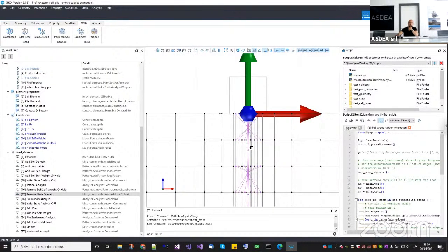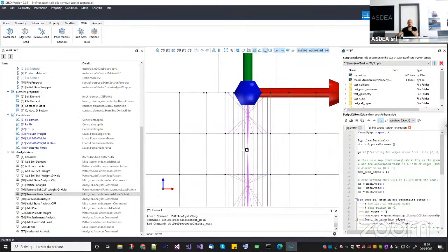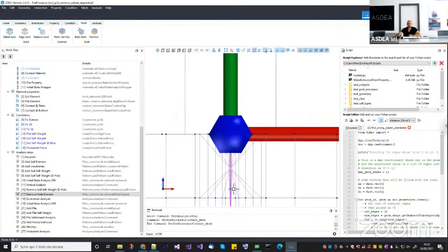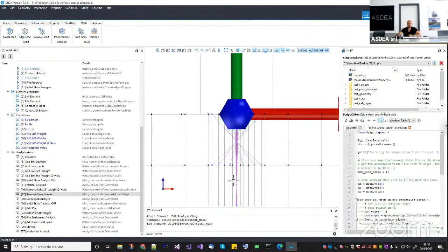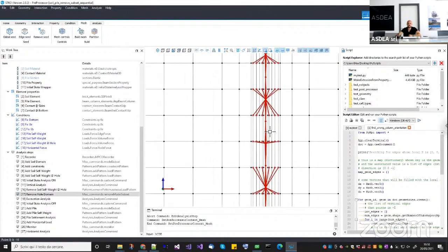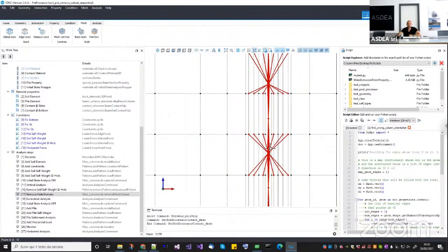So one solution, as I did, is to use a mesh seed on the beam which is quite larger. Otherwise, if you want to use the same mesh size, you can take the line of the beam here and apply a small translation on top, for example. If you apply a small translation on top and you assign the same mesh size, you will see the beam nodes being at the same level plus a small tolerance.